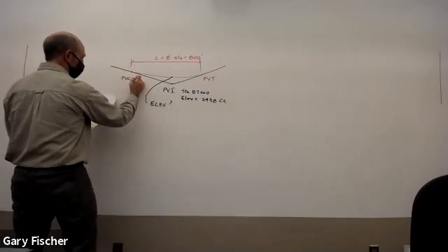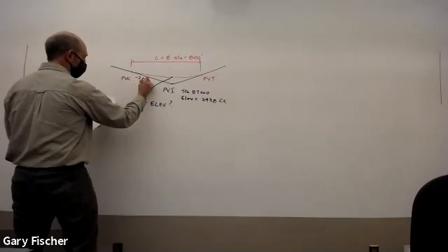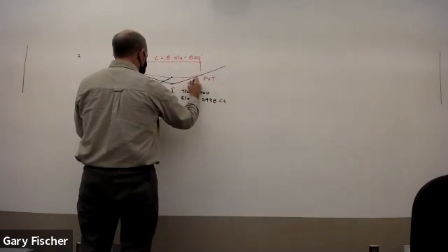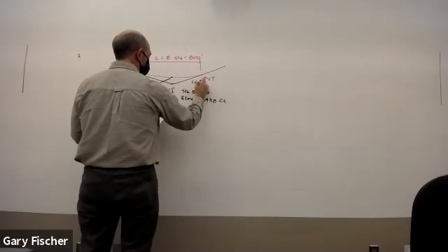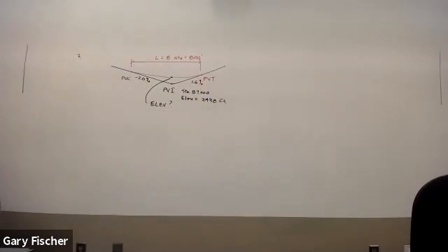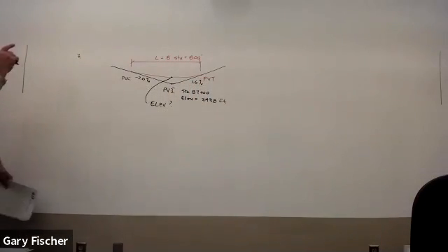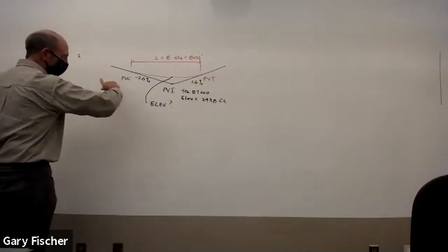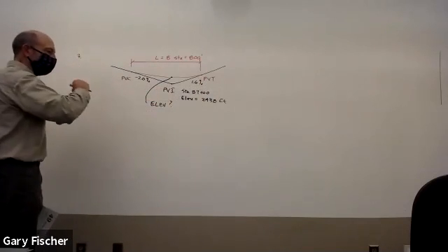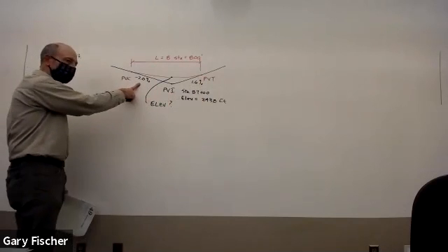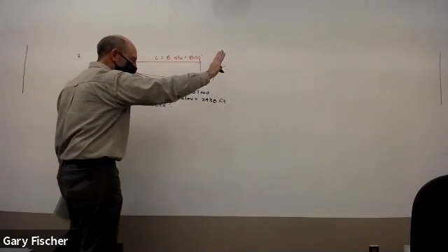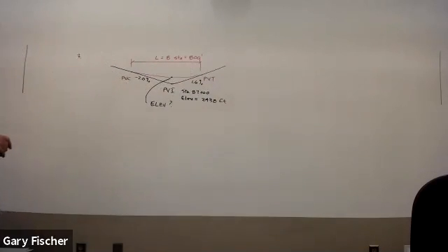Oh, they also give you the slopes of these lines that come out here. So this is a minus 2.0% slope. This is a positive 1.6% slope. The flow of travel goes from left to right. If you're going downhill in the direction of travel, they give it a negative slope. If it's going uphill in the direction of travel, it's a positive slope.